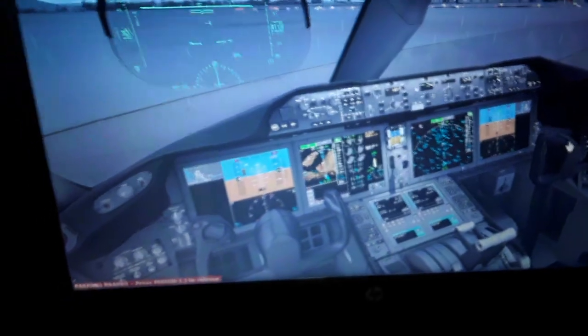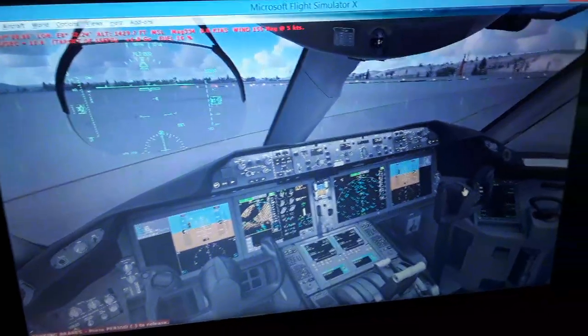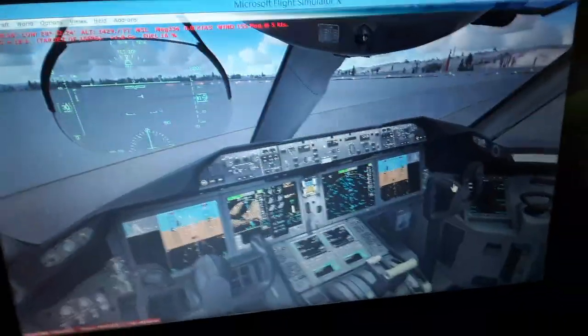We have also the HSI that displays the horizontal situation indicator, the magnetic heading and track, and also the integrated flight plan display. You can see the flight plan. We're going to create a layer using the flight management computer, so we're going to have all the waypoints one by one. They're going to be connected with the flight plan line as we're flying. We have also terrain and weather reflections from the weather radar. You can see the terrain map displayed in the navigation display with red, green, and yellow amber indication.